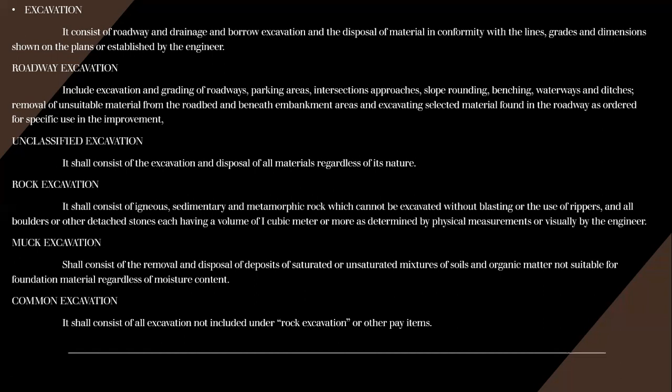So the roadway excavation includes excavation and grading of roadways, parking areas, intersections, approaches, slope rounding, benching, waterways and ditches, removal of unsuitable material from the roadbed and beneath embankment areas, and excavating selected material found in the roadway as ordered for specific use in pavement.